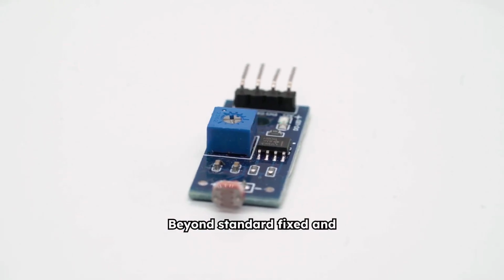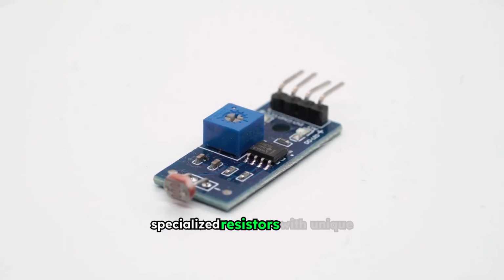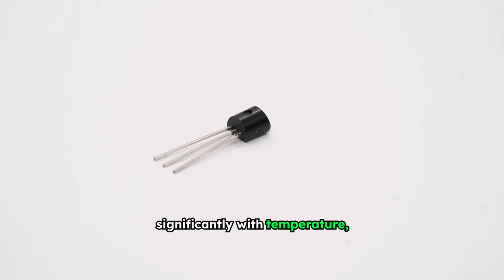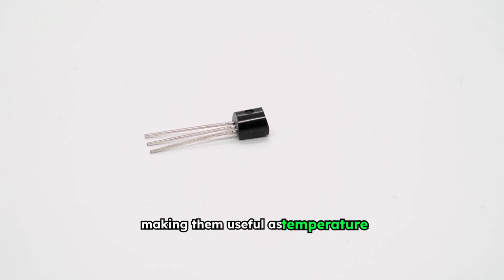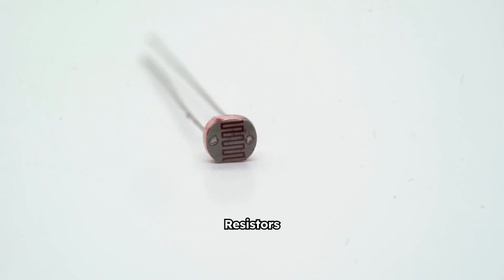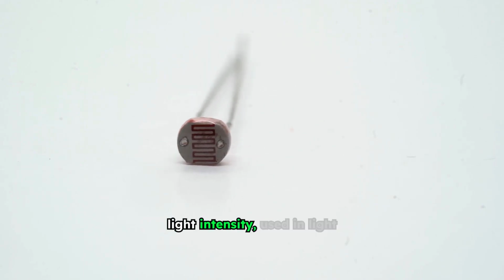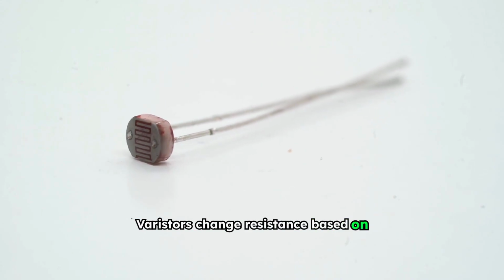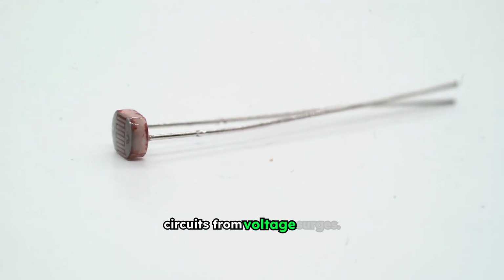Beyond standard fixed and variable types, there are specialized resistors with unique properties. Thermistors change resistance significantly with temperature, making them useful as temperature sensors. Photoresistors, or light-dependent resistors, LDRs, change resistance based on light intensity, used in light sensors. Varistors change resistance based on voltage, protecting circuits from voltage surges.